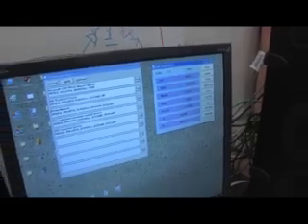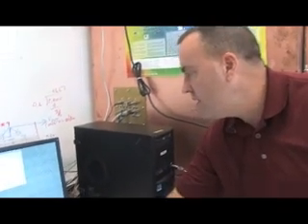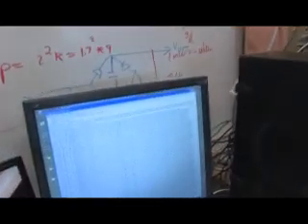And what we're doing now is we're logging all the data from the button presses and from the XY tracking. So if I close the application now that we're done, and I open up the log file, what you will see is a whole bunch of data. And what we do with all that data is we post-process it, and we look at things like lost packets, or we look at the timing between packets. And we use that to ensure that our products meet our requirements for no data loss and for acceptable latency. So that's an example of an interference testing setup that we use.